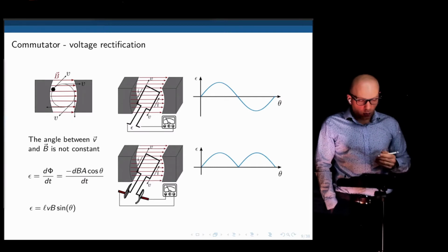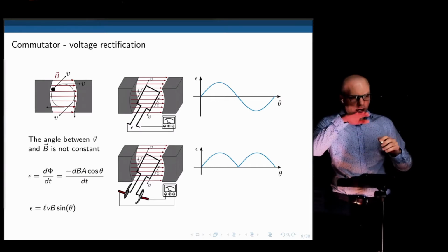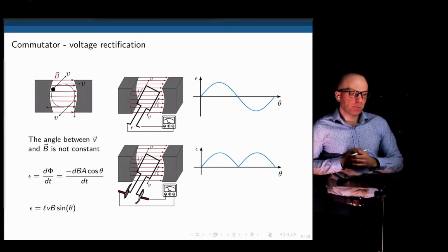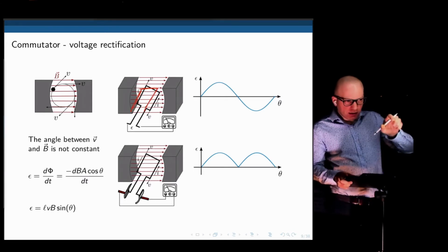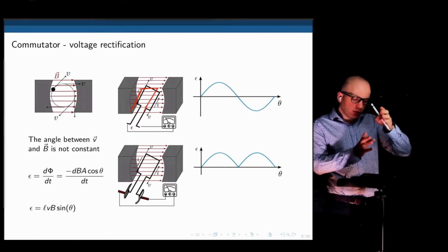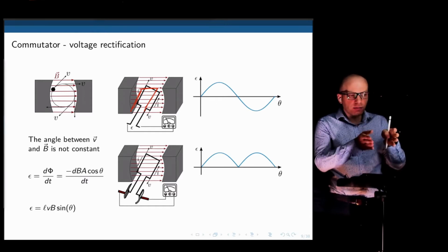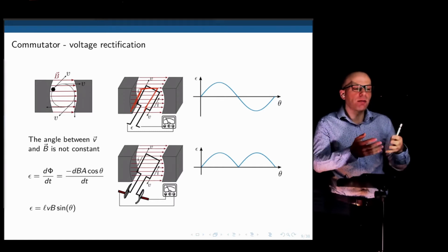That is to say that when the wire is flat at a 90-degree angle with respect to the magnetic flux, so we have the wires, let's say, like that, and this is starting to rotate, we see that it's crossing the highest number of magnetic flux lines. Hence, at that instant, the specific point in time, we'll have the maximum EMF being generated.